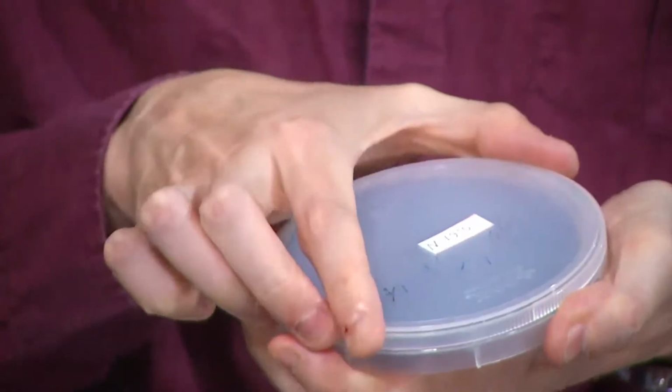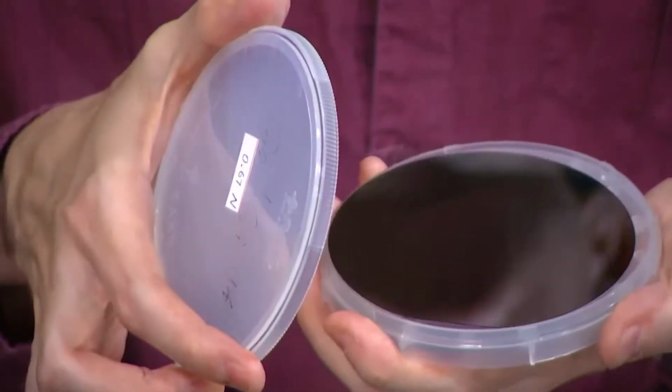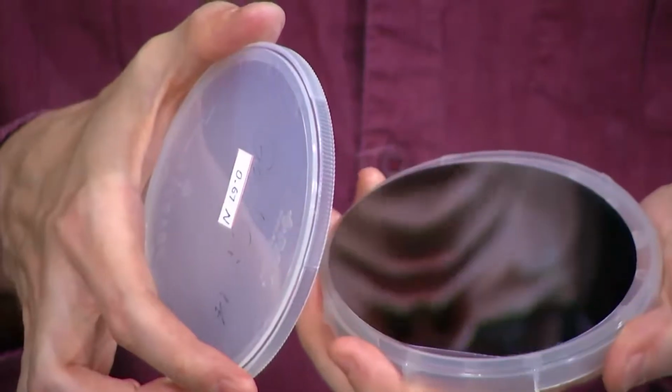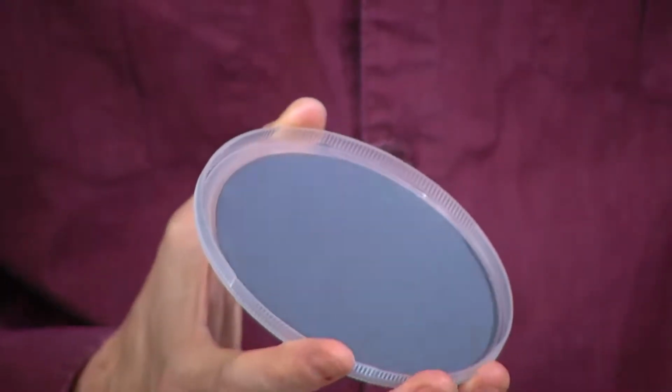And if you look at these wafers up close, they look almost like a mirror because they've been polished. And sometimes wafers are polished on both sides, and sometimes they're polished only on one side. Anyhow, the processing of the silicon wafer into a bunch of microchips is always done on the polished side of the wafer. Silicon is obviously not transparent. The wafer that I'm holding right now is just polished on one side, so if I turn it over, you can see that the reflection is quite a bit duller because the back side hasn't been polished.